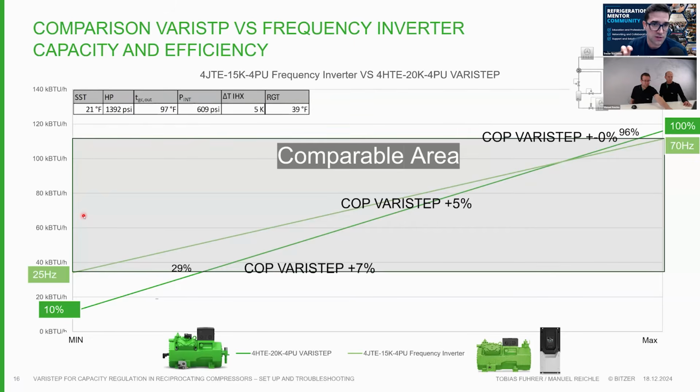Because as the technology starts to evolve, we're making it easier and easier to work on this equipment with the IQ modules and the way the manufacturer's set up. But you're going to have to reach out to them to double check that. Like, is this 1 or 2% worth it versus the complexity potential? And who's going to work on it afterwards, depending on what part of the world you're in? Do you have someone that can go out and service frequency inverters or something that's a mechanical control? It all comes back to the controls, but that's what you've got to think about before designing a system.